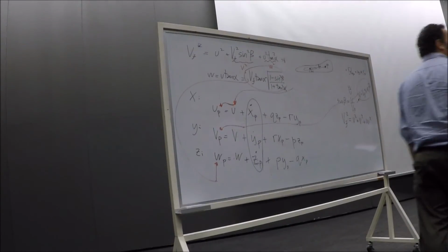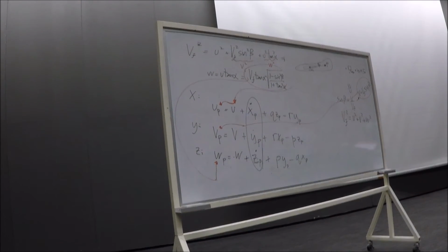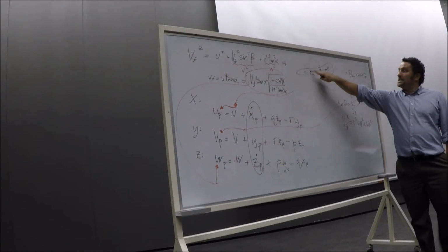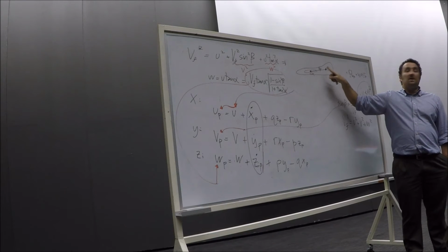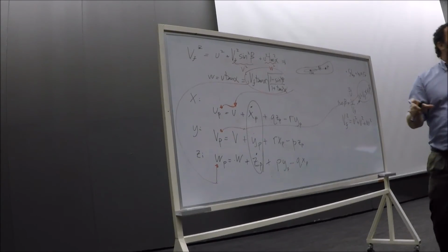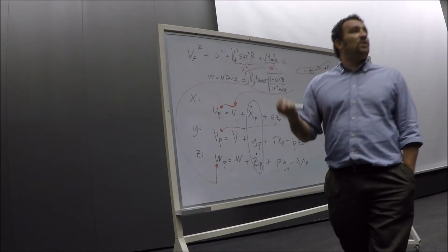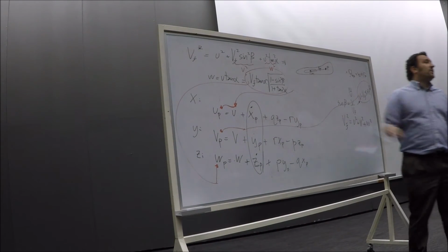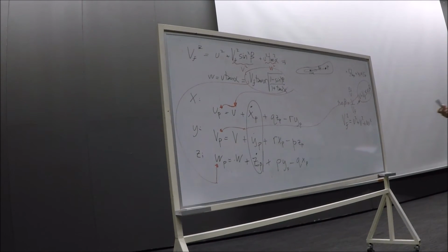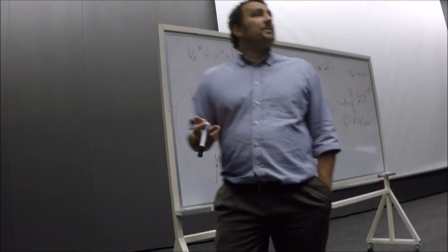Now, for most first order analysis, assuming that the aircraft is a rigid body is a fair assumption. If the aircraft is a rigid body, it means that there is no relative displacement between the 2 points. So if there is no relative displacement, there is no velocity. So as a first approximation, you can assume that r_p is constant. But for a more precise and detailed analysis, you need to take into account the flexibility of the aircraft. Okay?